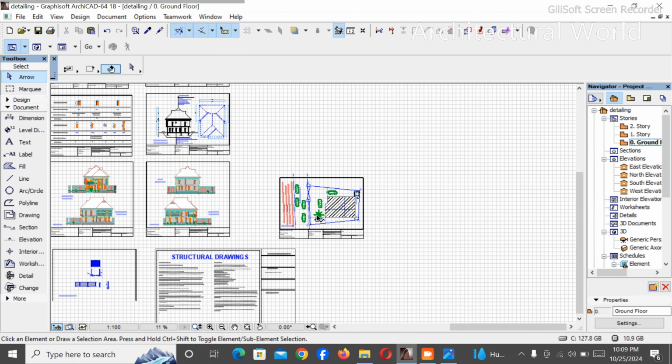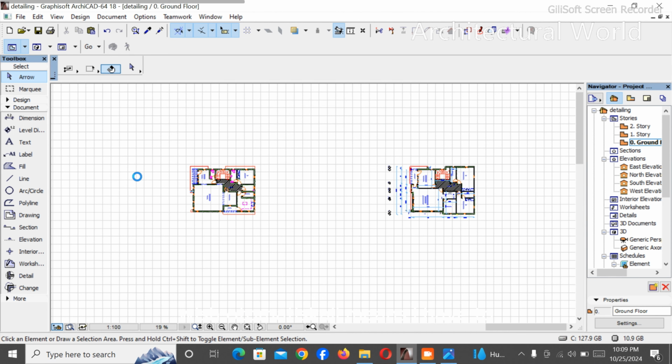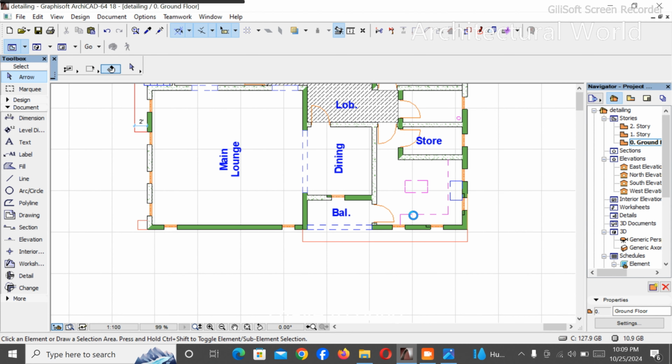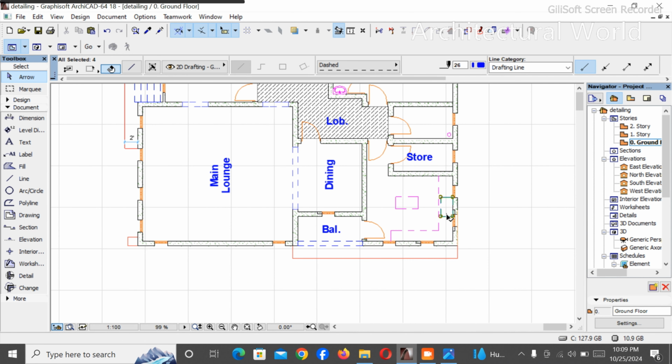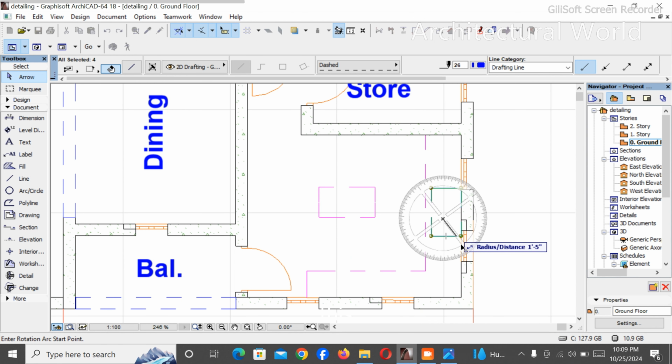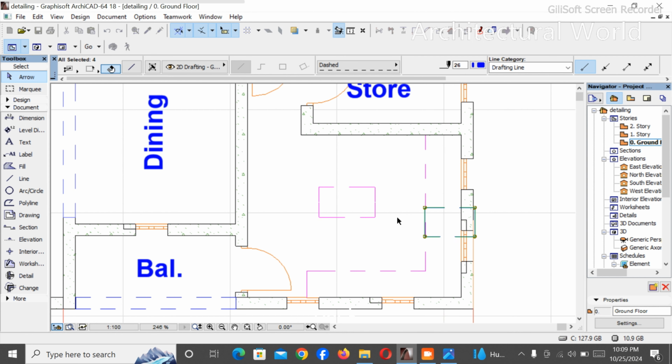So if my soakaway is at this end, it automatically means I have to bring this back. If my soakaway is at that angle, it's best I have this toilet seat, this kitchen sink on this section. Let me show you. This toilet seat is basically best on this section.